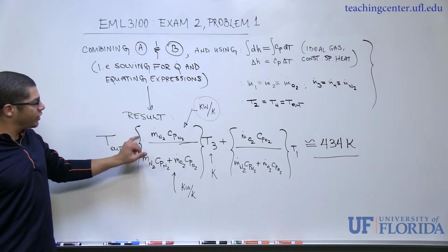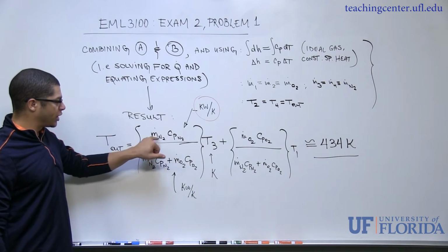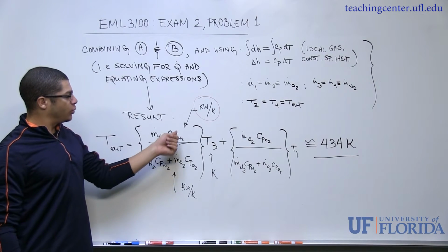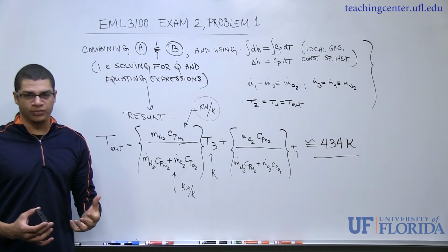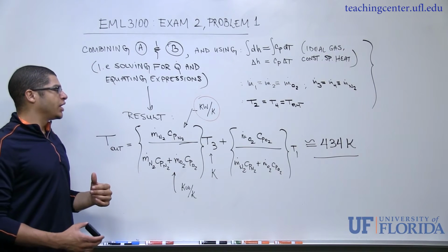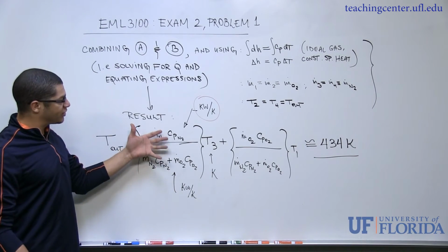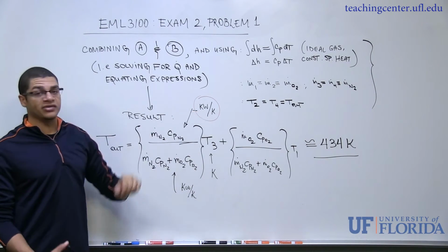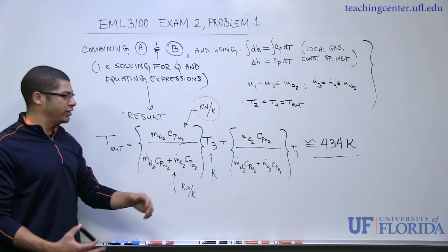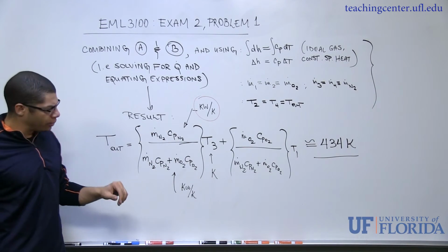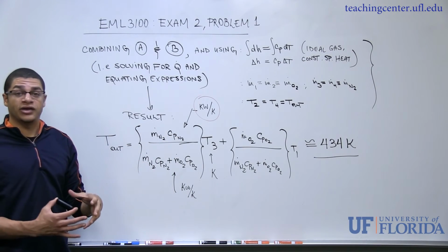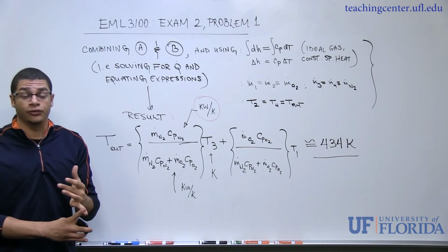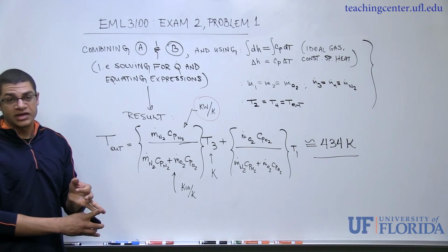And it's worth noting, if you look at the units, once we multiply these together, we've got kilograms per second times kilojoules per kilogram Kelvin, and the resulting unit is kilowatts per Kelvin. Because we have an open flow system and we're dealing with heating rates, this is the thermal capacity in terms of the heating rate necessary to raise the temperature by 1 Kelvin. And once you plug in the numbers, you'll see that the nitrogen side actually has a bit higher capacity than the oxygen side due to the fact that it's got a higher flow rate and a higher specific heat capacity.